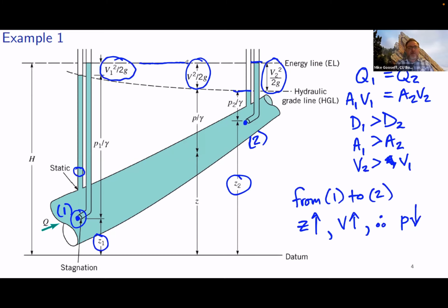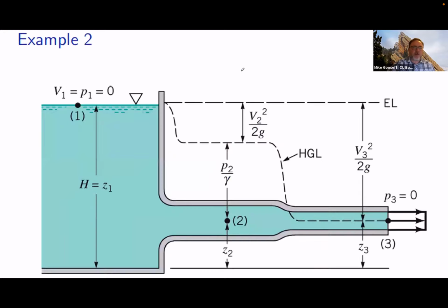If we want to measure the velocity head, then one easy way to do it is to instrument our flow or our apparatus with both a stagnation tube and a static tube to be able to measure that difference. And this difference here is that velocity head, right? And that exists all along the pipe. Okay, so that's where we're going with this concept, that we can apply Bernoulli's equation at all places to learn something about how all of these energies vary amongst each other.